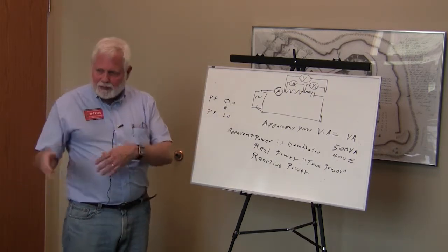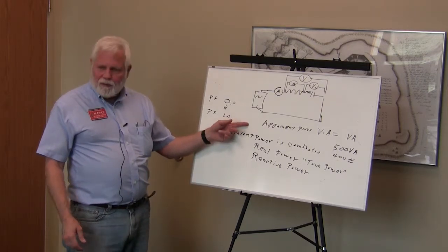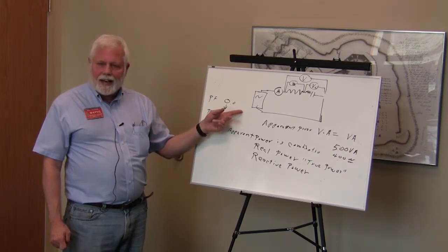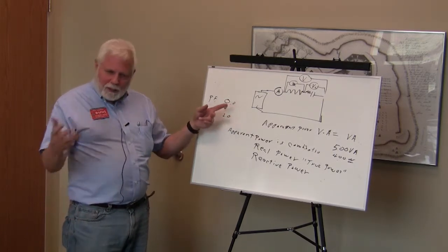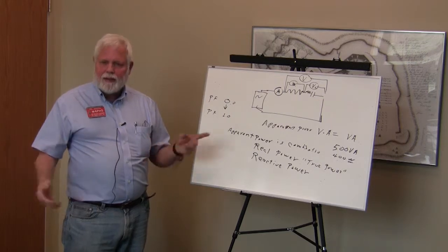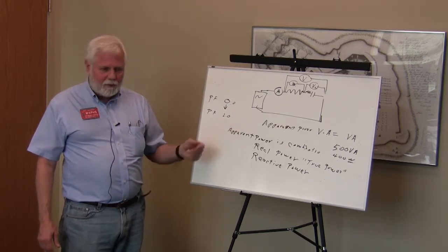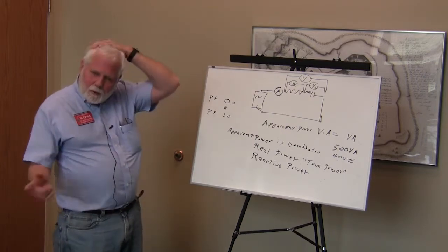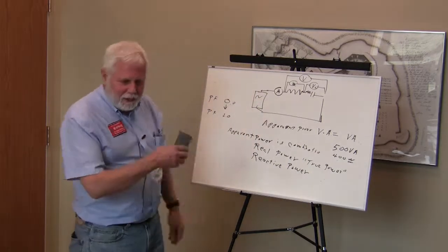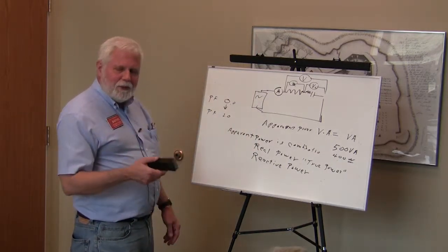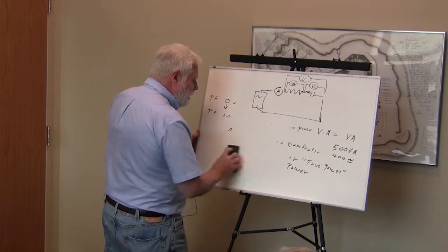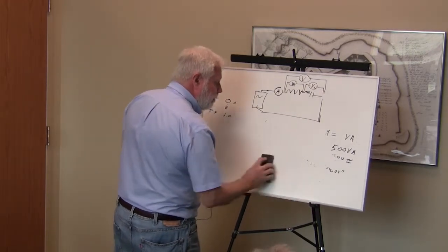Now for big commercial companies, there are reasons why they don't like power factors less than 1. I won't get into it here. You can talk to me after class if you want to, but the electric company doesn't like you to have a power factor less than 1. They realize you're going to, but they don't like it. If you're a big industrial company, like an aluminum plant, and your power factor is way off, they charge you for having the power factor off. They may charge apparent power rather than true. But for the home residential user, it's measured in true power, and you don't have to be concerned about that. You're doing some things which are not ideal from the power grid point of view, but don't be concerned about it.